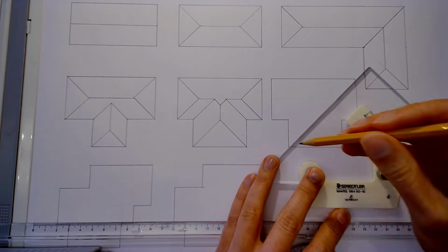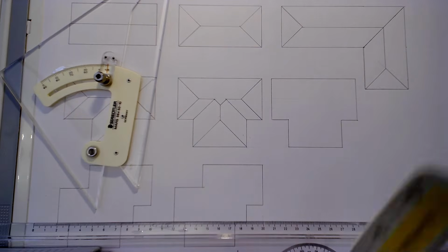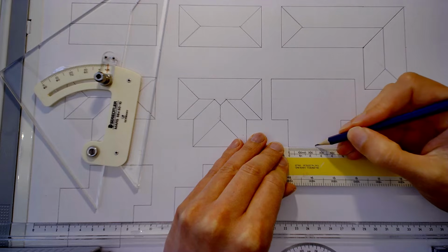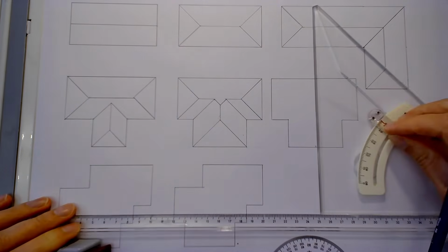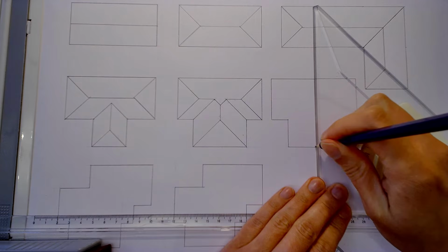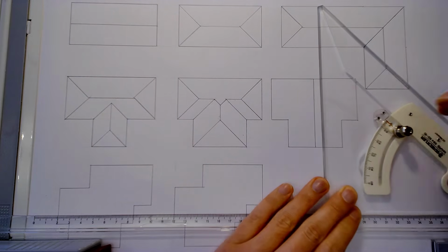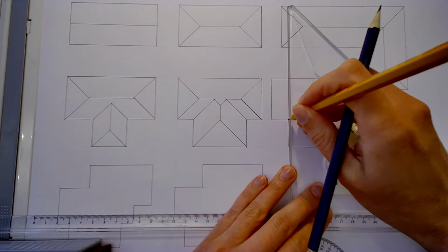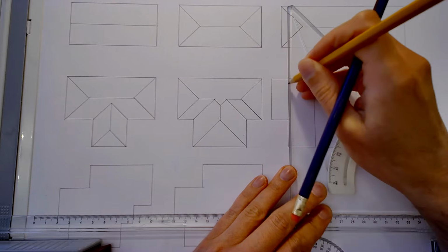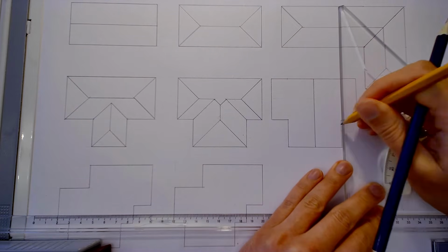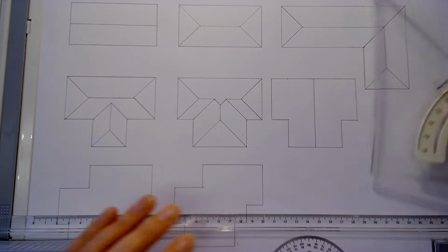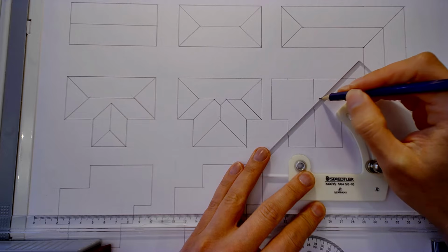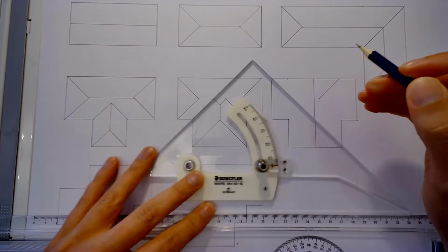The other option you could do, which might be simpler from a roof construction point of view, is actually to go back to using a gable, and we're going to measure the halfway point here and have a gable running down there like that, and then we can mark out that wall position on the far side of the building, and that is going to be a valley coming up to the centre point, which I've already just sketched across there.